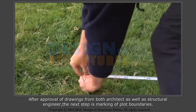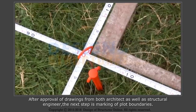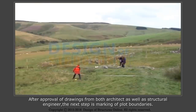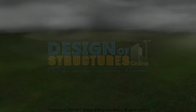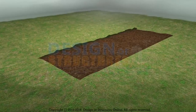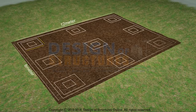After approval of drawings from both the architect as well as the structural engineer, the next step is marking of plot boundaries. Cleaning of plot. Site preparation consists of clearing away the trees from your building site. This involves the removal of trees, roots, and other vegetation from the building site. After cleaning the site plot, marking of the plot should be done as per drawings.